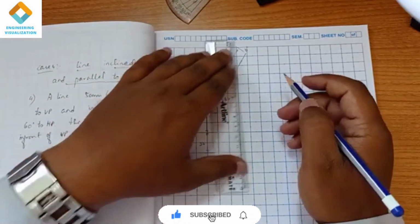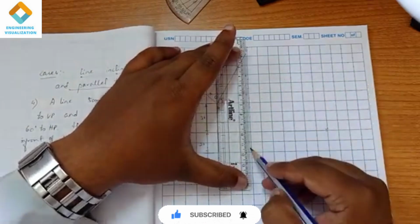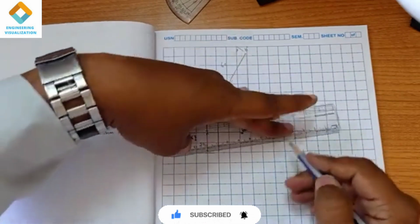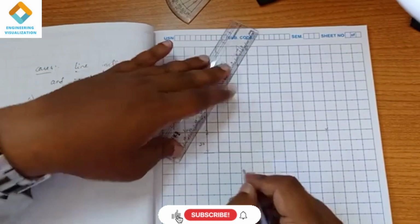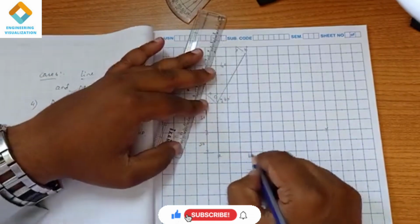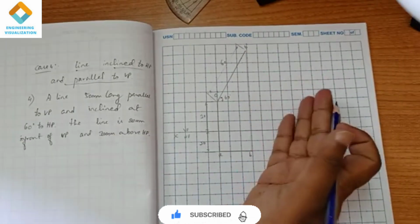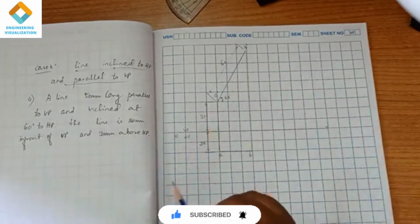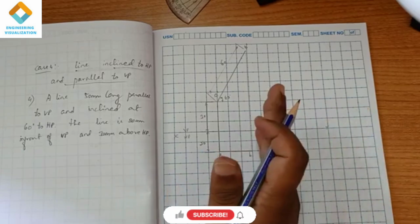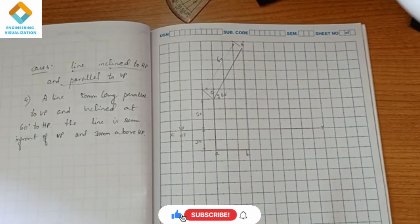Now projecting downward, we get the length of the line here. This is our top view, AB. The inclination to the HP is shown in the front view, that is in the vertical plane. So it is inclined to HP and parallel to VP. So this condition is also done.